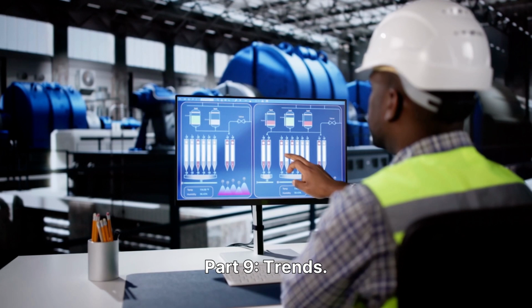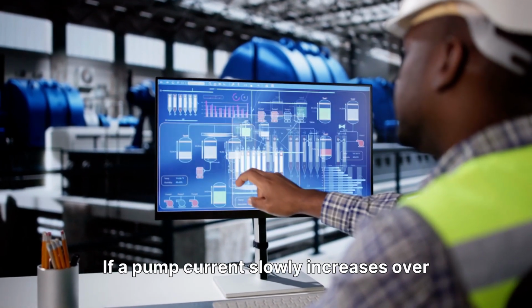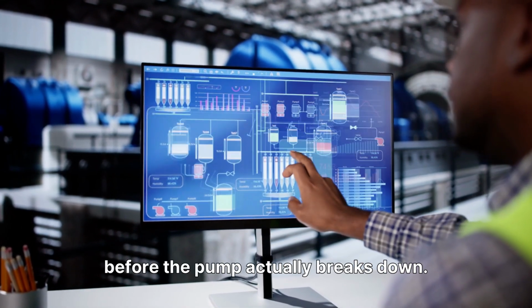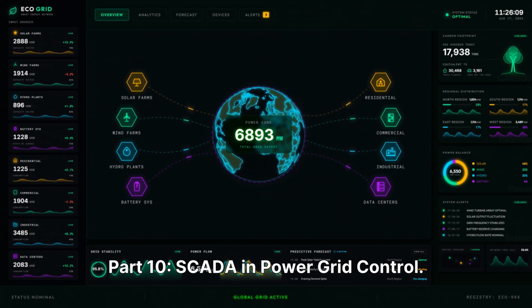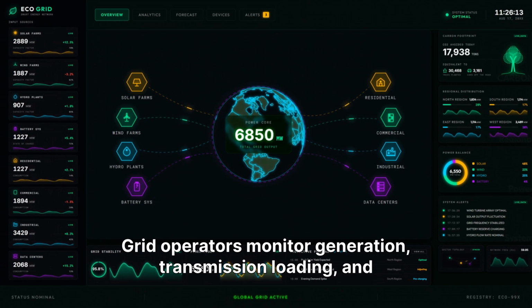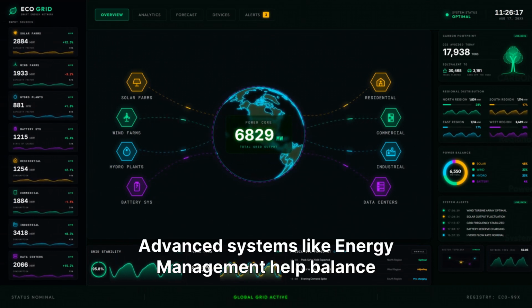Part 9. Trends. Graphical views of values over time. If a pump current slowly increases over weeks, trends reveal the friction or blockage before the pump actually breaks down. Part 10. SCADA and power grid control. Grid operators monitor generation, transmission loading, and frequency. Advanced systems like energy management help balance the whole grid.